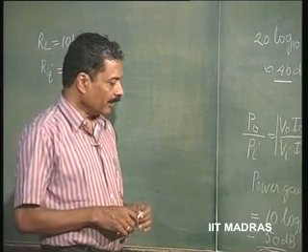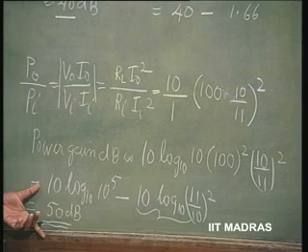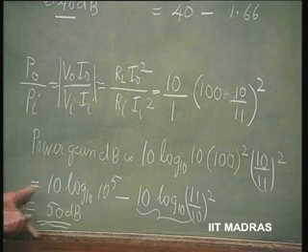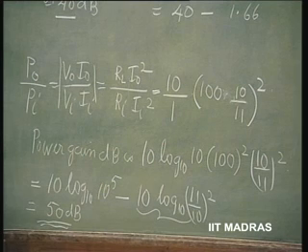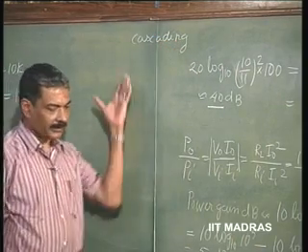That can be readily found out from how many decibels is your requirement in terms of amplification. If it is 100 decibels in terms of amplification that is required for power, then you know that two such stages must be cascaded. If it is 150, three such stages must be cascaded. We will discuss this later, how to do cascading to improve the power gain of stages.